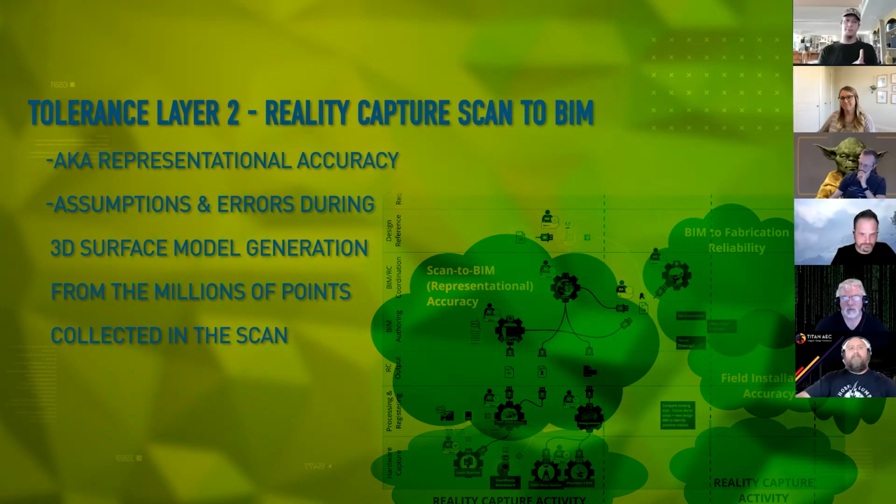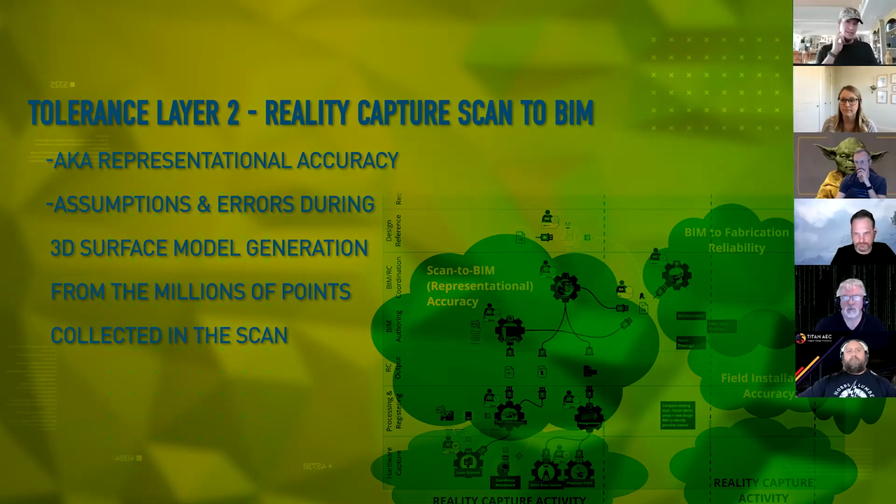No, not at all. Great point. And I think somebody mentioned early self-leveling scanners, and I quipped, but seriously, self-leveling quote unquote scanners use an IMU for their verticality, and it's about an order of magnitude less accurate than scanners with live compensation in it. A dual axis compensator, you'll hear DAC.